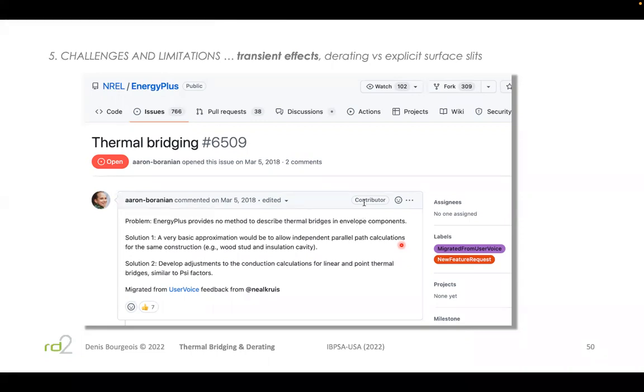So there's a second part to that question. My understanding is the original R value requirements were somewhat arbitrary and based on typical wall constructions at that time. I actually sat as a standing committee member in 2009-10. So the effective R values that were required actually came from ASHRAE 90.1, a draft version of the 2010 edition. And you had those exact values, but ASHRAE rolled back those numbers by the time they made it to the actual standard for public review. But the Canadian codes kept those numbers. So I would say my general impression is that those values are somewhat arbitrary and not determined by any type of building stock assessment and practical assessment.